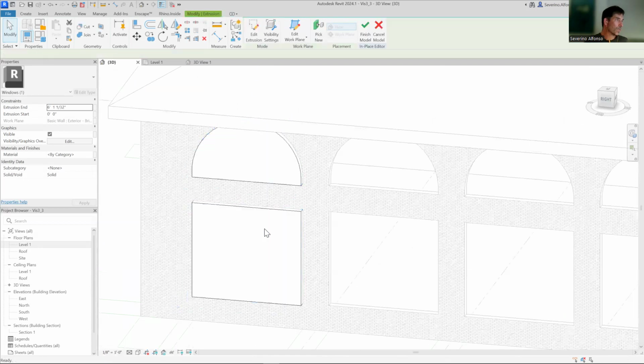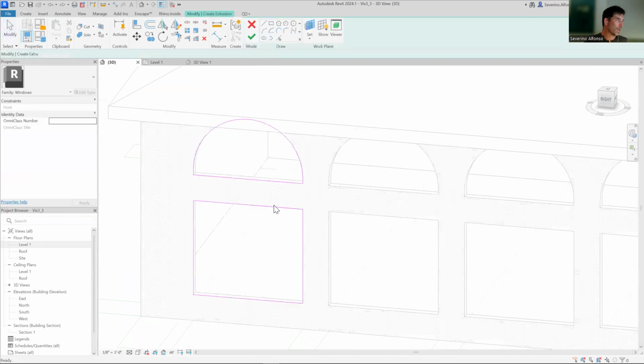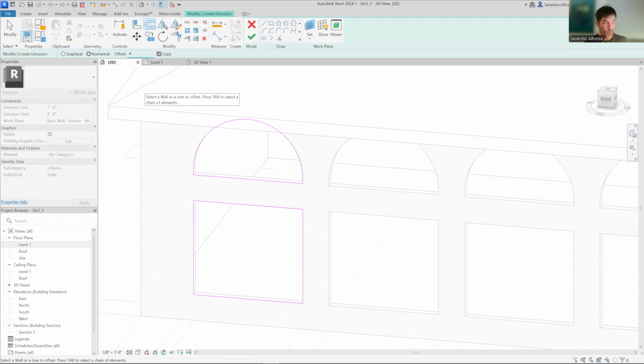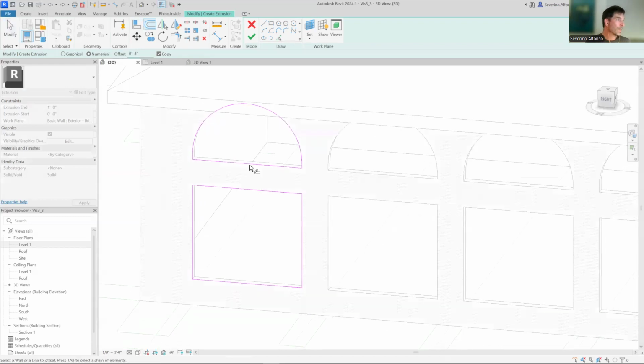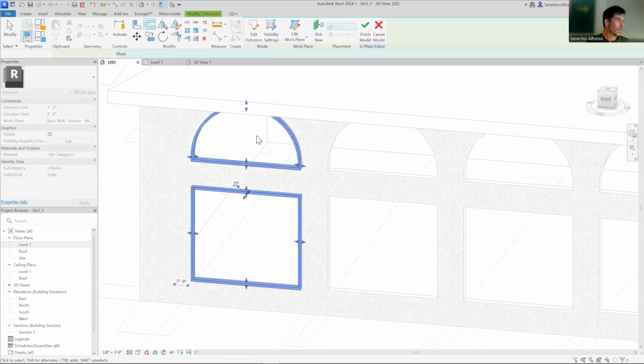this situation, which is not exactly what we want. So I'm going to go back and back. What we're going to do is an offset, OF, and then we need numerical, and not for feet, but for inches, more or less. This allows you to do an offset of a line, but if we click the Tab button, it selects the chain of lines. So again, you stay on top of one with the dash line looking to the interior, Tab, click. Same goes here, Tab, click. So we could already say okay to that.